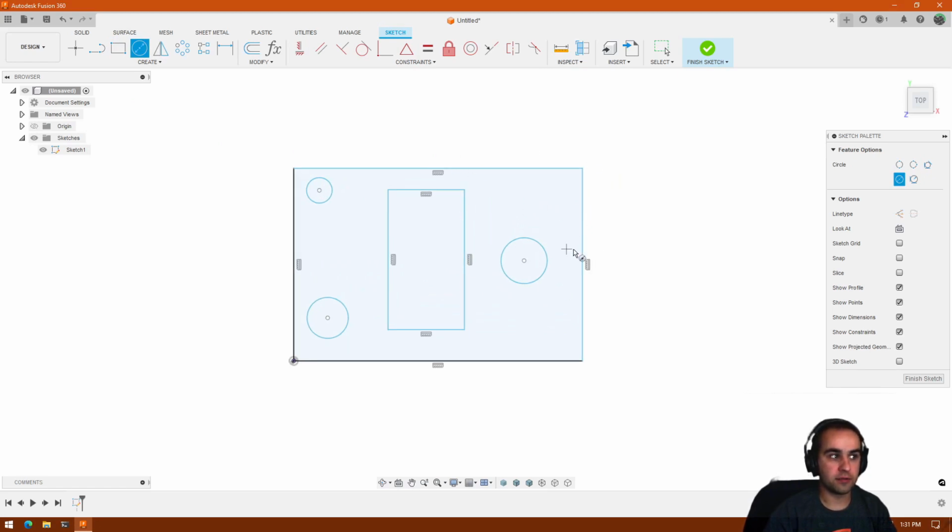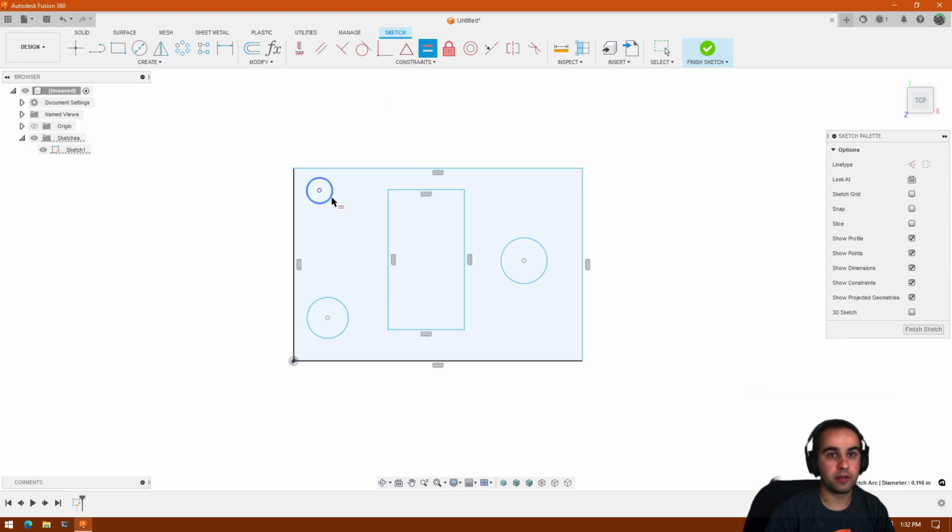So now we have a basic sketch with some different elements, but right now everything's just kind of placed where it looks right, and we need to go through and set the actual locations and sizes. So the main way you'll do that is with this dimension tool, or you can also in some cases use geometric constraints as well. So let's say that, to start off, let's make all the holes equal size. So say equal this hole to this hole and this hole to this hole.